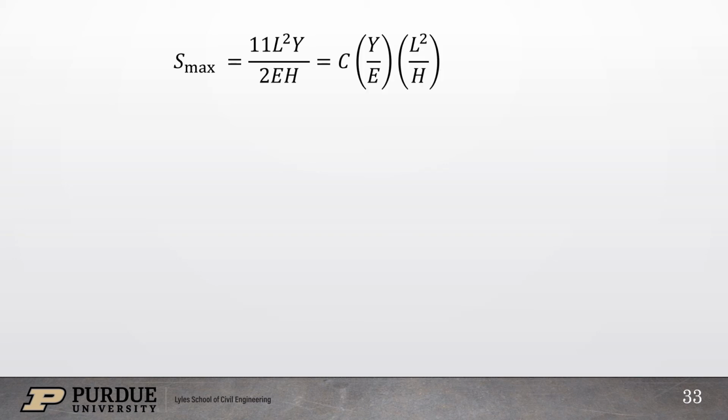Before we go any further, let's try to understand where this geometric ratio came from. This is the equation which is currently being used by the code. We can rewrite the equation by separating the material component and the geometric component, where L is nothing but the distance between two measuring points, which can be substituted as the perimeter divided by the number of measuring points.